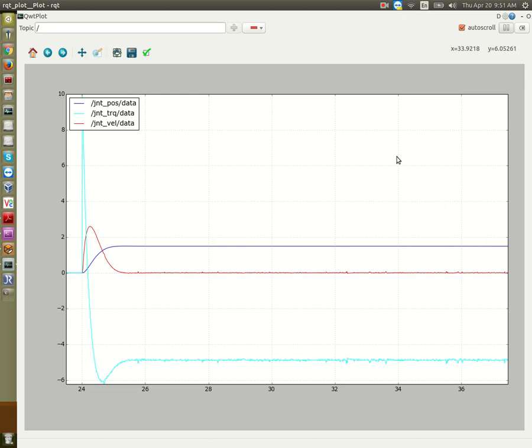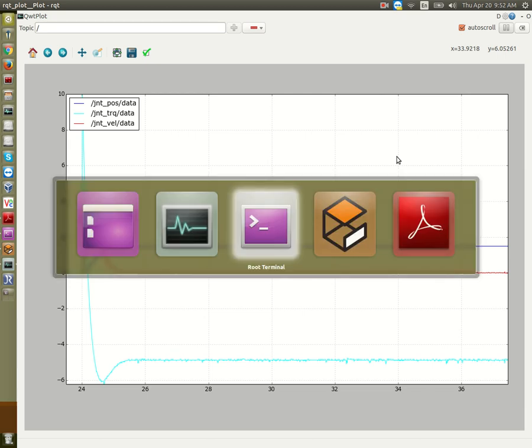So it's very nice, right? You have the node listening for topics. That comes in, goes into the controller, it does an error computation, it updates the torque command. It computes the torque command, and then it begins to move the arm by sending the effort. This would be great for you guys to go back and use GDB on this with Emacs or any IDE you want to use, and go line by line after you publish the command, to see how this is working.